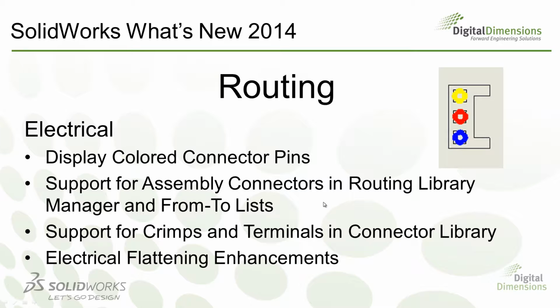The second thing I wanted to show was that there's the ability to now create an assembly connector. In previous releases you could only make a part connector. Now you can have separate leads and a back shell and other pieces added, so it can now be an assembly connector, and that is supported in the routing library and in from-to list. So I will show this now in SOLIDWORKS.